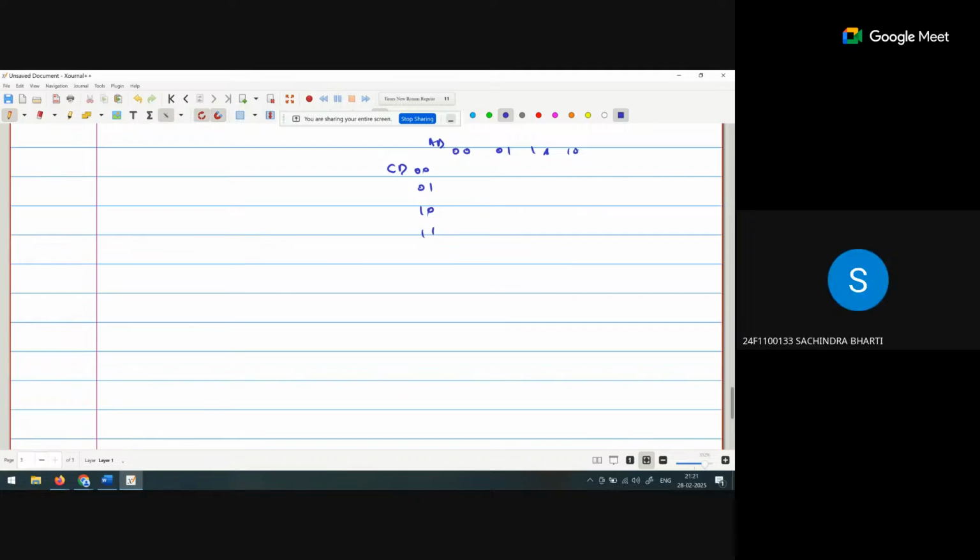Sir, just you do 1 or 2. That is okay, you write 4. How do you write minterm 4? The combination of minterm 4 is A is 0, B is 1, C and D both are 0, 0. So 0, 1, 0, 0 is the 4. So here I mark. Remember that your sequence A, B, C, D is always maintained. You can't mark here, it is wrong.